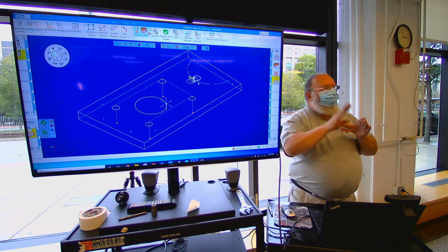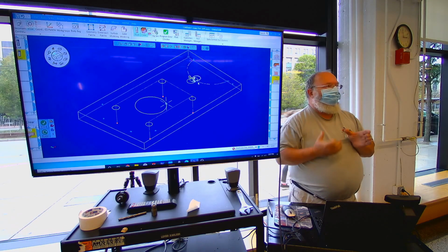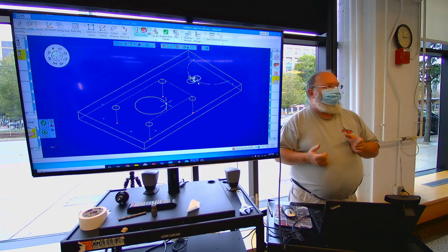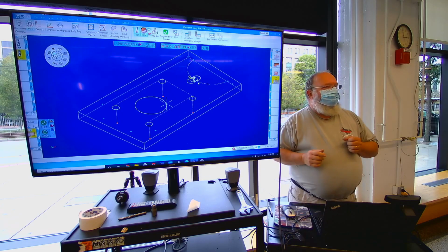When I say eliminate it, we reduce it down to the 4th decimal place where we can tell the control to compensate for it. It actually is called out in the control as backlash compensation. So that's what allows us to do all of this high volume climb milling.